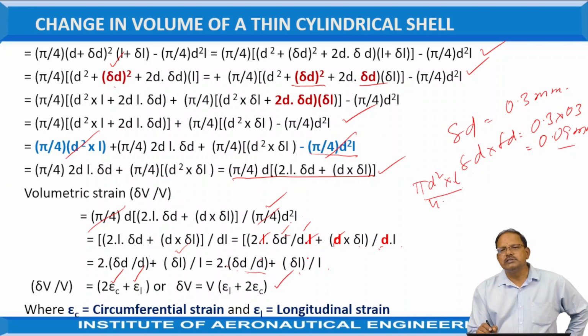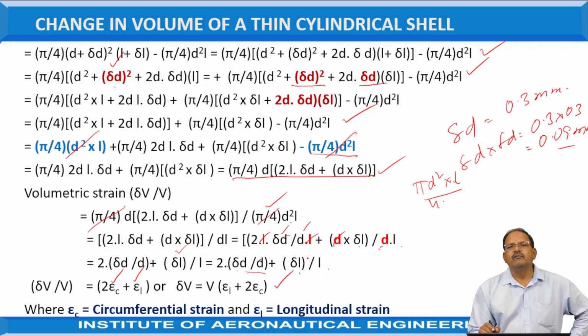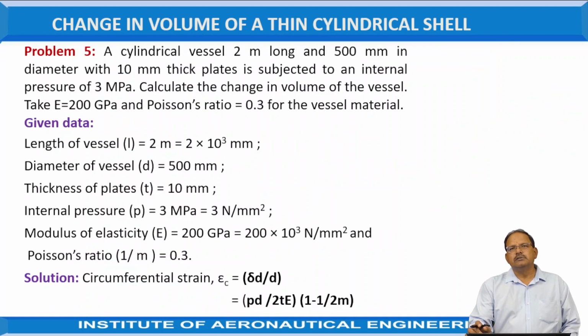So by using this equation we can determine the change in volume of a cylinder when it is subjected to internal pressure, and also the strain, that is the volumetric strain, that is produced within the cylinder. Based on the change in volume of a thin cylinder, this is one problem we are taking now.